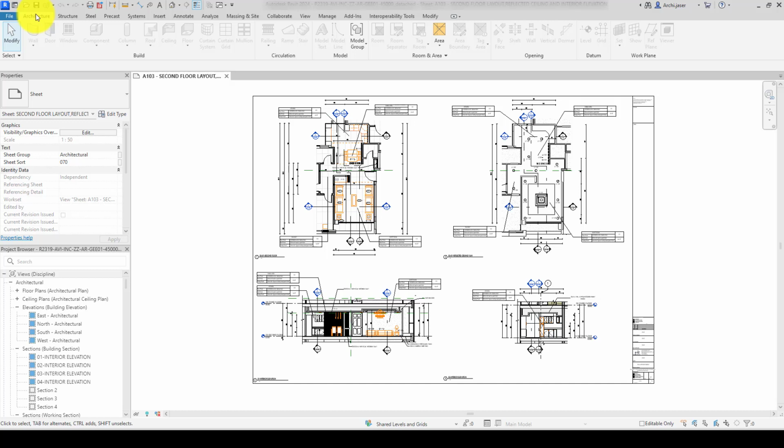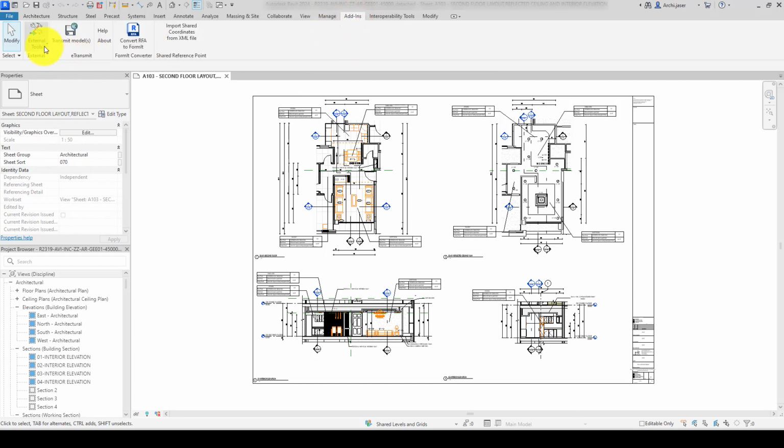You can install it. But before moving from REVIT to Navisworks, you need to export your models from REVIT into a different format. And from that format, you will be using the different software. In order to do that, guys, your IT needs to download something we call Navisworks Exporter.